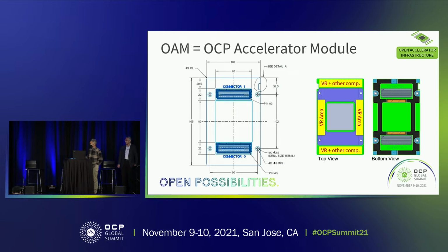And then on the side, we have approximately 80 millimeters between the mezzanine connectors, and from the X, it's about 30 millimeters. So you can see from the areas that we actually have, it's not a lot, and the components are very tightly packed around the SoC.